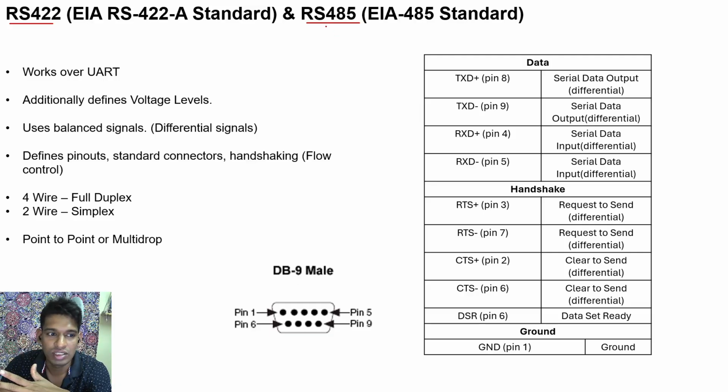Both are comparable, but RS-485 is an even better standard. Now again this works over UART. RS-485 is again a communication standard which works over the UART interface. By interface, what I mean is that the communicating chip underneath is using a UART IC.